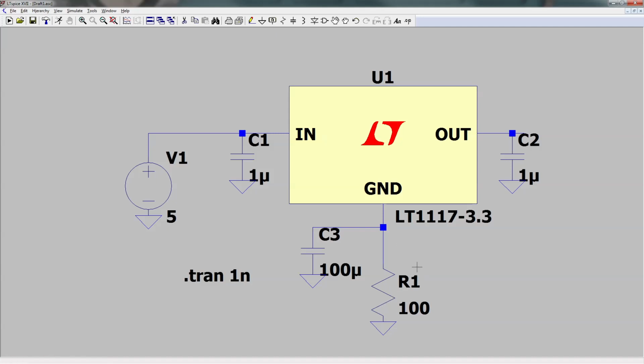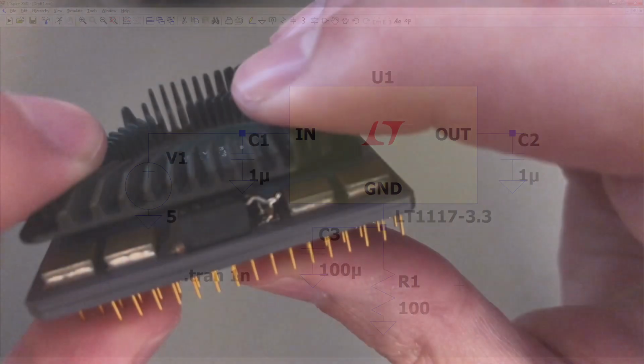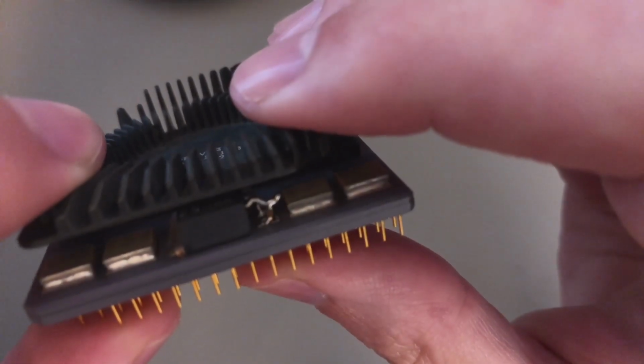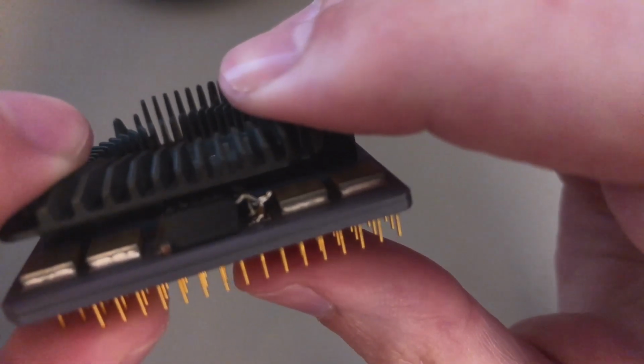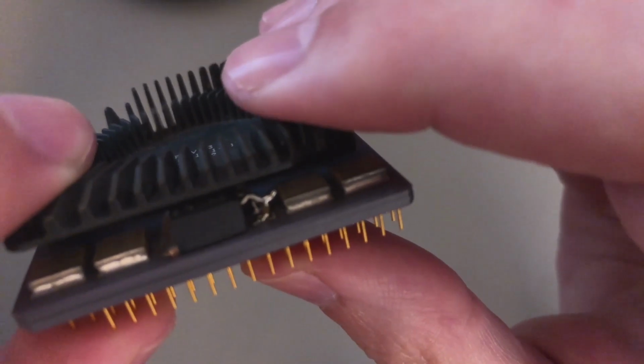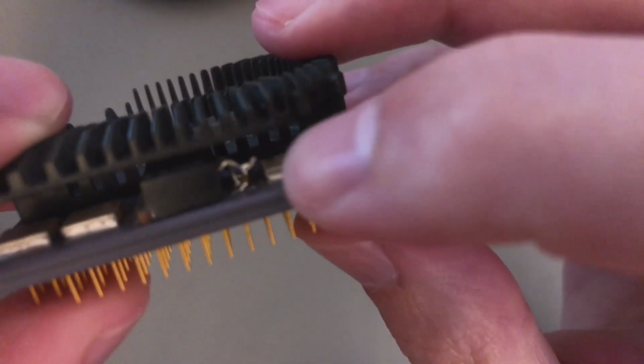Also, of course, here you can have a variable resistor, and in this case something like a 200 ohm one is more than enough. So when I first started playing here, I hit the limit very fast. And okay, first of all I did this very fast and dirty mode of just placing a very small Schottky diode here on the ground pin.